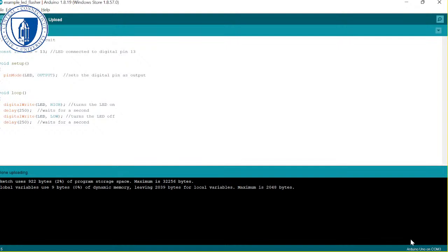So the nice thing about Arduinos is that they've got no other operating system getting in the way, right? So they can deal with stuff in what I'd call close to hard real time. If you've got an operating system like Linux or Windows or the Green Hills one or Wind River's, that's not too bad because they actually do like doing real-time stuff. But Linux generally and Windows, unless it's the really good embedded one, which is a new version, they get in the way of doing real-time stuff. So things get delayed because the operating system is off doing other things.